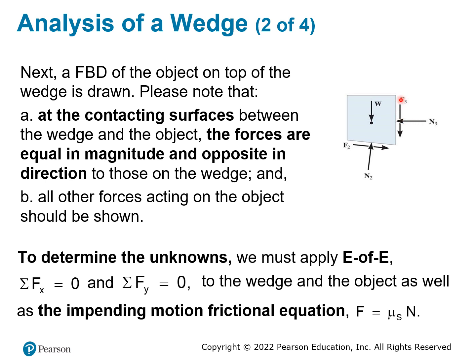And you also have friction between the wall and the object. Now think about the direction of the friction. This object tends to move down. However, when you push the wedge in, you are lifting this one up. Because the intended motion of the object is going up, the friction is going down.